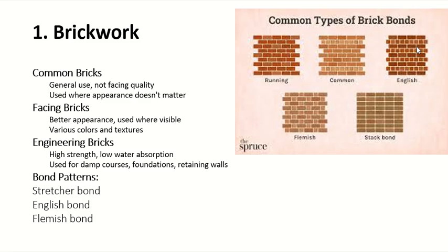With the grid type of structure, the last portions of the wall are normally wasted, and you have to break the bricks. With the other types of bonds, you have less wastage because it is uneven, so you can put small parts of bricks somewhere as well. So you have running bond, common bond, English bond, and Flemish bond.